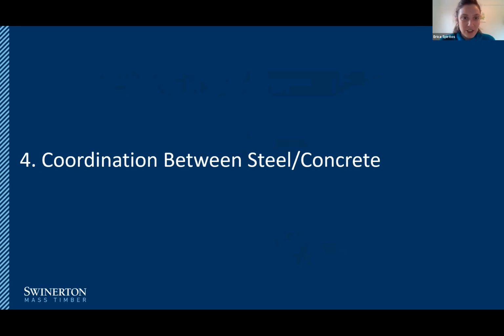James MacArthur asked, no fire protection, so fully sprinklered. Yes, the building will be fully sprinklered. And the fire protection is in the form of upsizing of the timber members to provide that sacrificial char, and in encapsulation of some of the timber components with usually 2 layers of gypsum wallboard sheetrock.